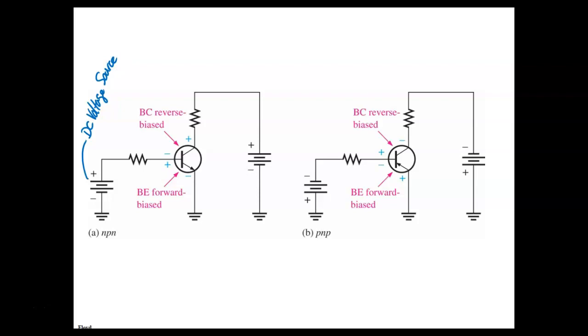So it could be a battery. So this is two-battery bias, which we're going to do. Notice on this one, we're using common or ground common as emitters connected directly to common. So I have to make the base positive with respect to the emitter.